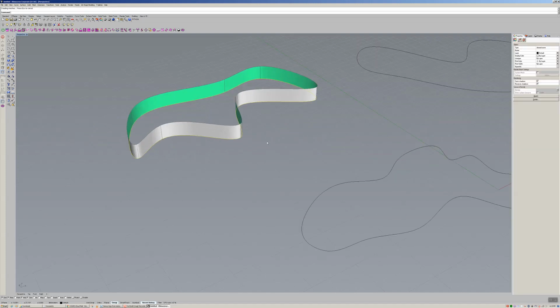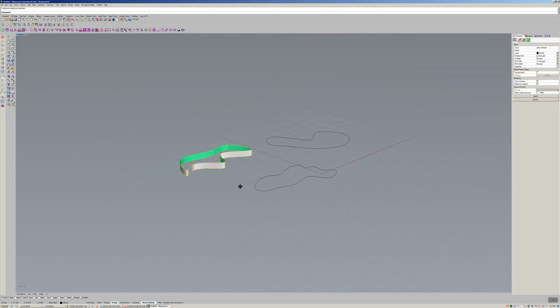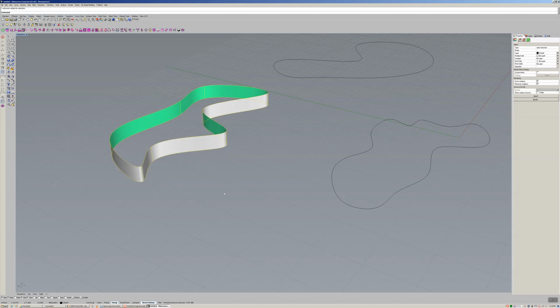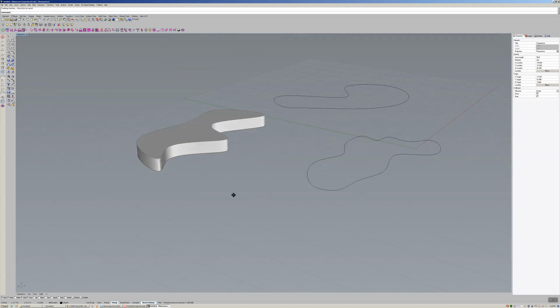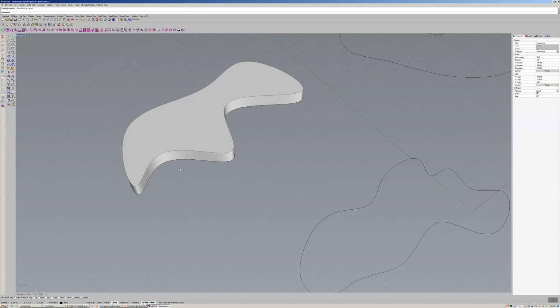So this is now what we call a surface. And 3D is building objects through surfaces. These are considered like the side of the walls with the top missing. Once I put a top and a bottom and it's watertight, that's a solid. And we can do that by hitting Control-C. And now it's capped. Now it's a solid object. Now this solid object is 3D printable.